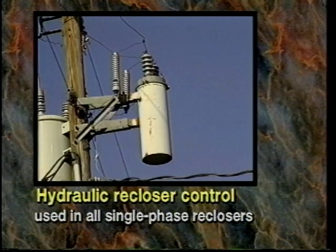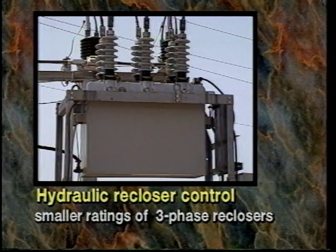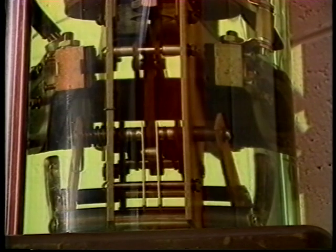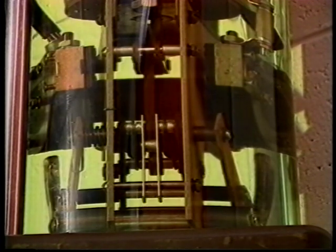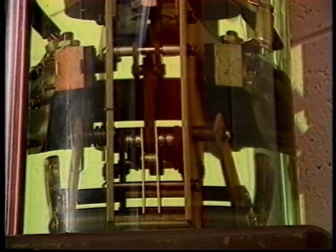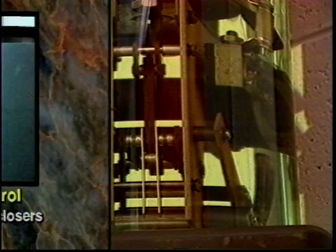Hydraulic recloser control is used in all single-phase reclosers and in smaller ratings of three-phase reclosers. It is built as an integral part of the recloser. With this type of control, an overcurrent is sensed by a trip coil connected in series with the line. When the overcurrent flows through the coil, a plunger is drawn into the coil to trip open the recloser contacts. Timing and sequencing are accomplished by pumping oil through separate hydraulic chambers or ducts.